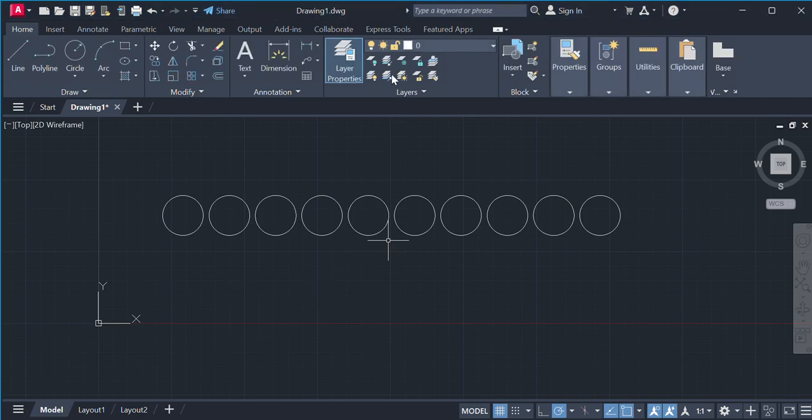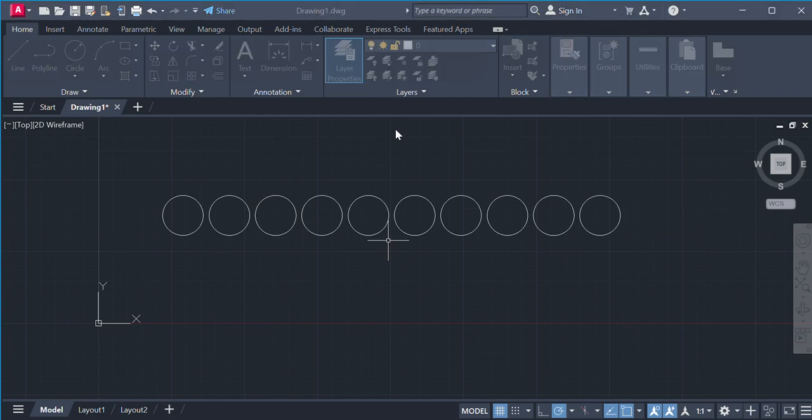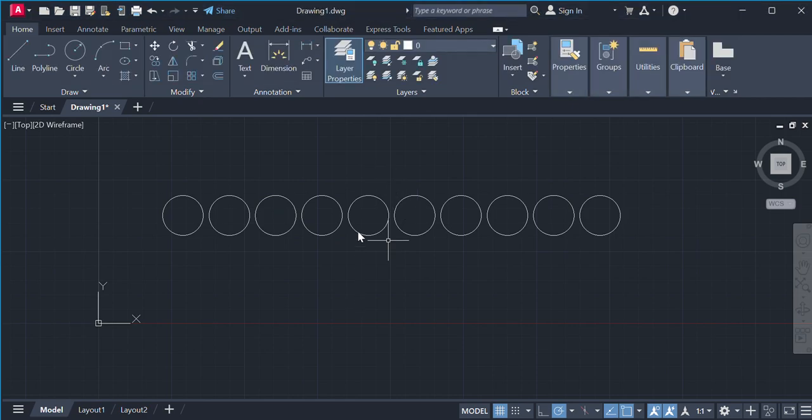Line weight, we normally just leave it as default, but you can compare this to the clutch pencil you used to use in Technical Drawing 1. For those that did Technical Drawing 1, it was a 0.5 or a 0.7. I know it looks really thick on this paper. That's why I really recommend that you leave this one as default, or a 0.15 if you really must be fancy. Then you can just play around with that. Okay?